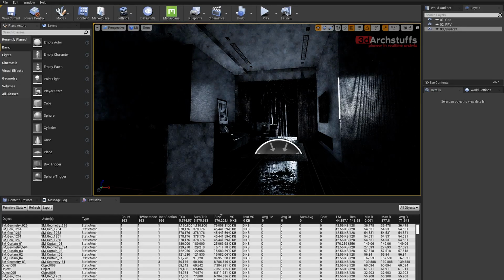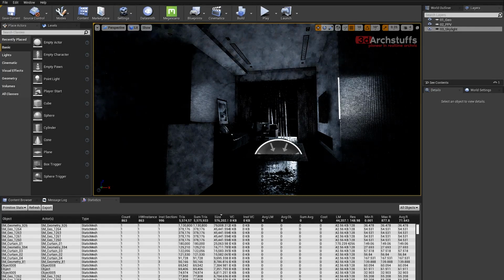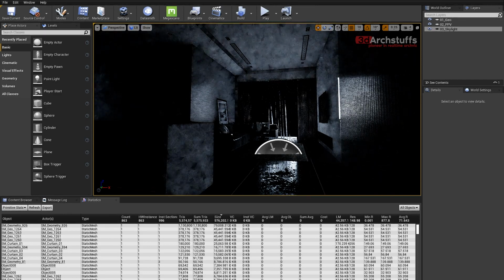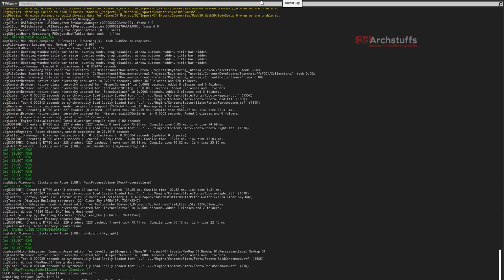That means if we start a new project and start working, then the GI denoiser is already on by default, and that GI denoiser is not accurate. That means it's bugged. It's not actually denoising anything. It's even making the denoising worse. So based on my experience, what you should do is press the up arrow key, which brings back the command which I gave, then press back, then press 0, and then press enter.